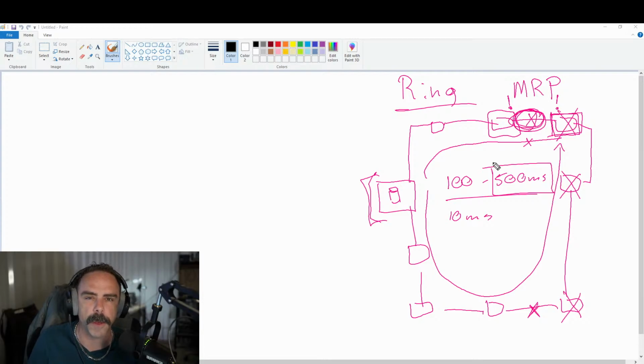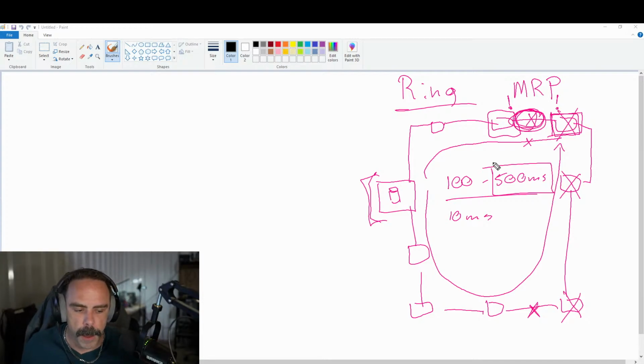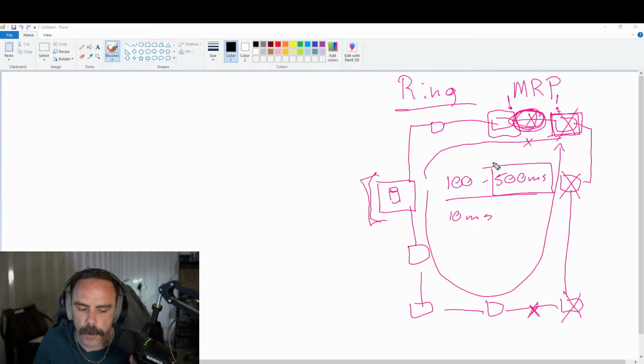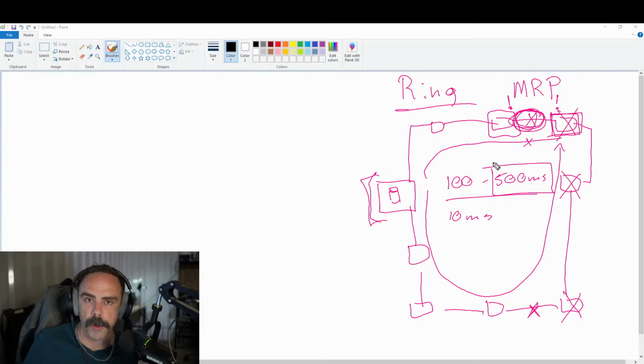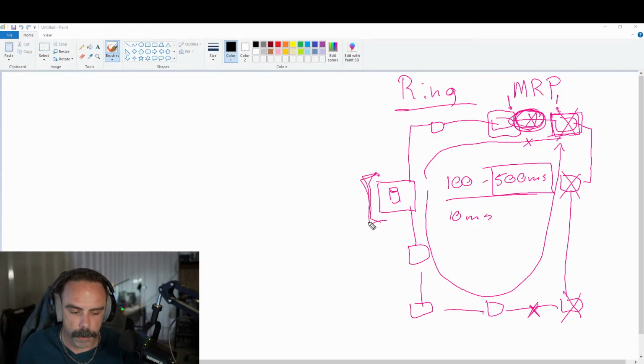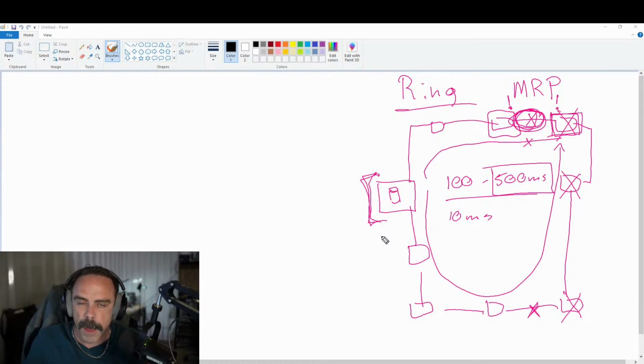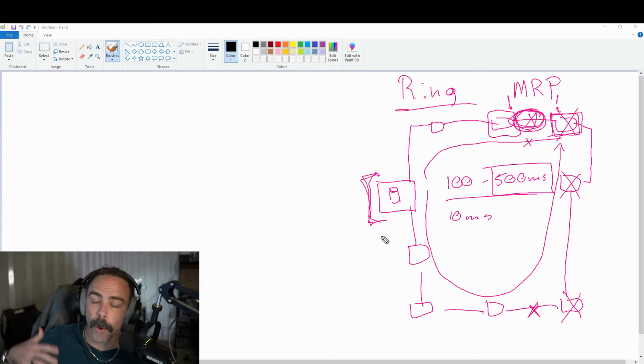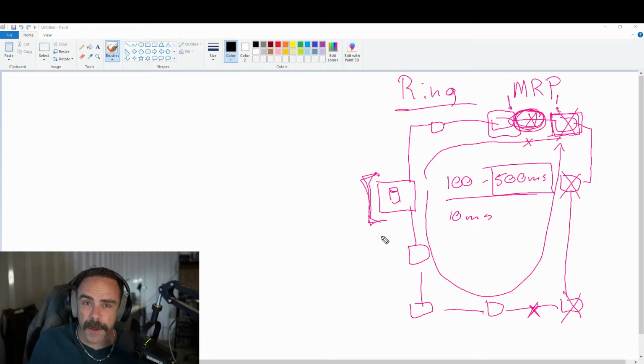We'll have to make some of those decisions, but MRP makes it to where you're only using 2 ports for your communication trunk on your main device, because if you only have 8 devices, that's a pretty cheap switch. If you have 18 devices, that's getting more and more expensive. If you have 30 or more devices, like we do at our plant up in Wabash, that's a really expensive switch, especially with the technology that we have.